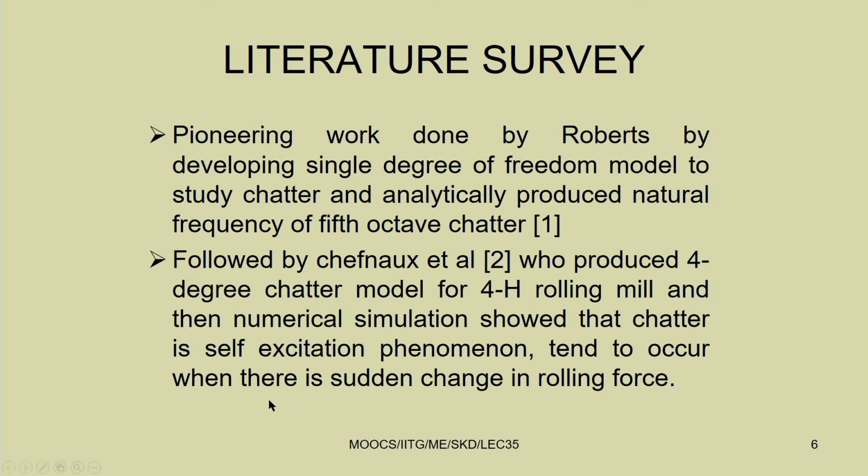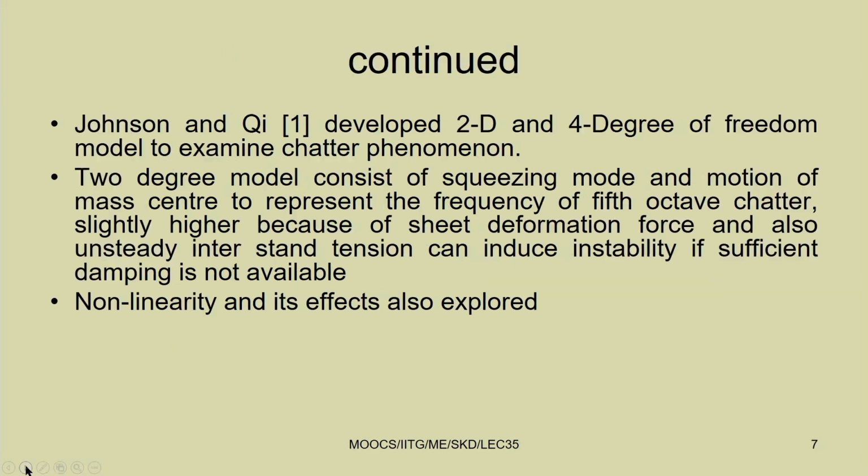They considered self excitation and showed that chatter is a self excitation phenomenon that tends to occur when there is a sudden change in the rolling force. So, this is a self excited vibration.